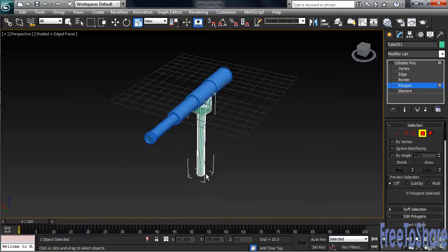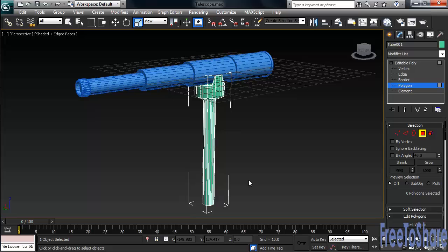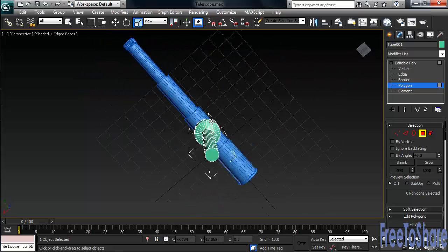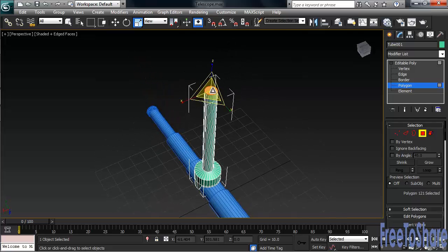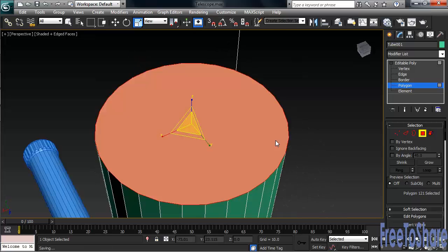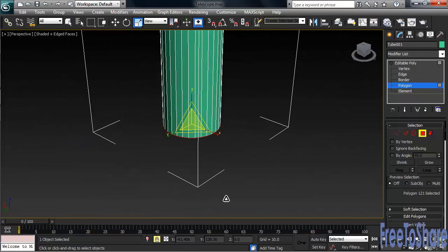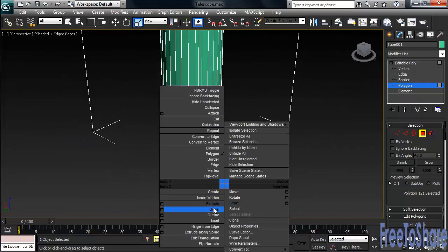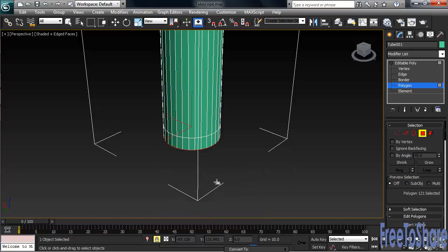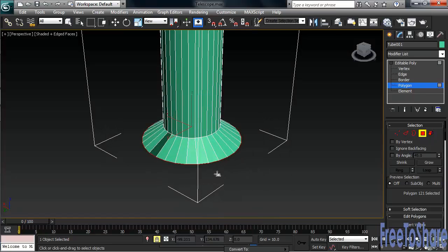To finish this out, let's put a base on our mount. That'll require us to go back down to the bottom of the post on the mount, selecting that bottom polygon. With that selected, I'll type Z to zoom in, then roll my wheel back so I'm not quite as close in. Let's lock this poly down again and orbit back to the top side. Now we'll create a bevel pointing down. We'll push down, let go, and then push out.